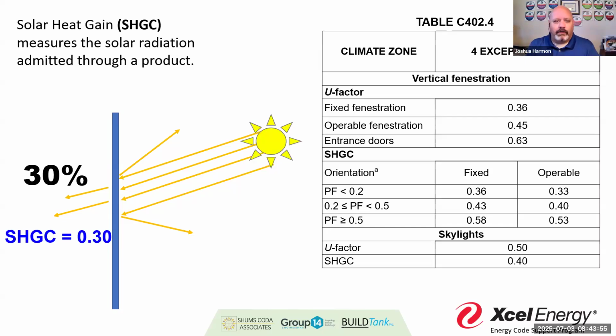But when we start thinking about that from the commercial perspective, this can have an impact based on orientation of the building, right? If I've put a more effective window system on a side that has less projection and more direct sunlight, then that's going to resist the solar heat gain, which affects how much that building is going to require for mechanical heating and cooling.